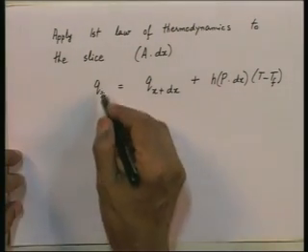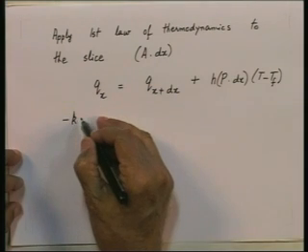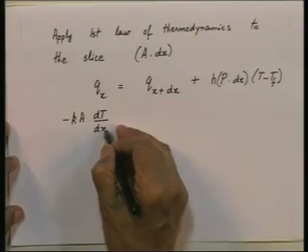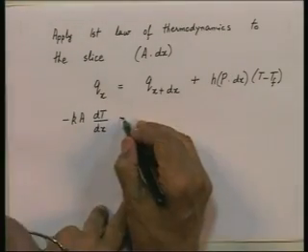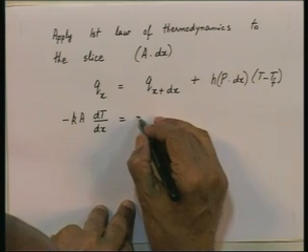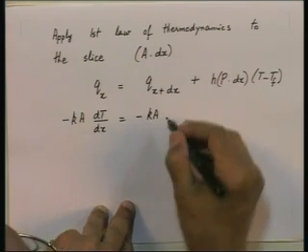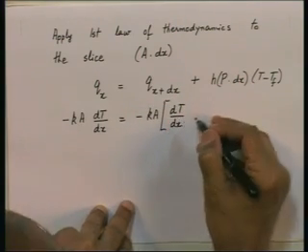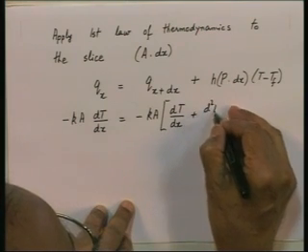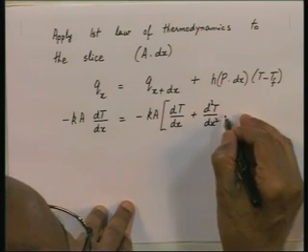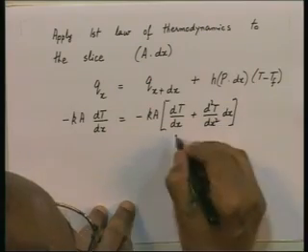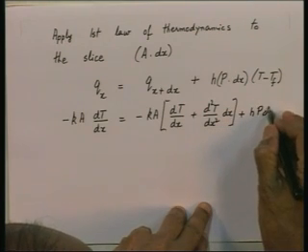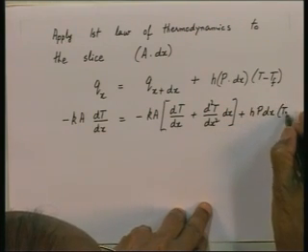Now, from Fourier's law, Qx is nothing but minus k A dT/dx, and that is equal to Qx plus dx, which is minus k A dT/dx. If I move a distance dx in the positive x direction, I will get d2T/dx squared multiplied by the distance I move dx, that is the increment on dT/dx, plus h P dx (T minus Tf).